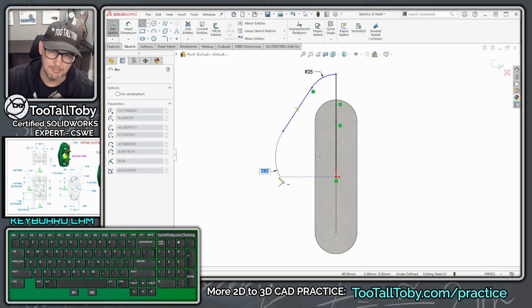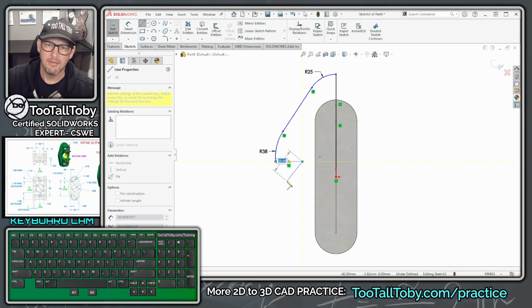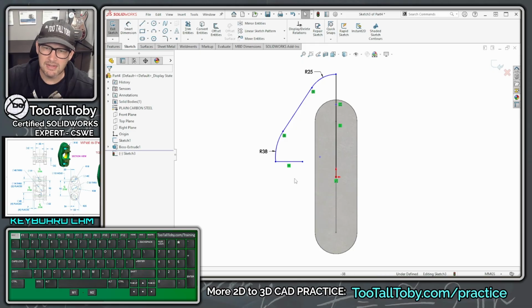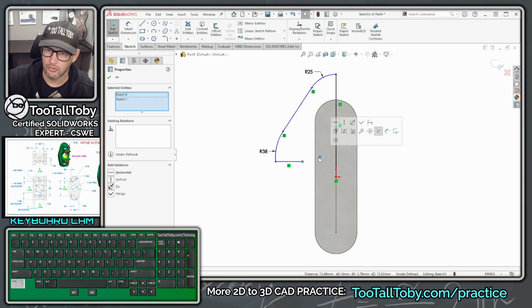If you're close, you can come down here horizontal to the origin, which is nice, but you can also just single click here, move your mouse over and single click again. Then you can hit escape, and then you can take this point, hold control, this point, which is the center of this arc, let go of control, and you can make those coincident or merge points.